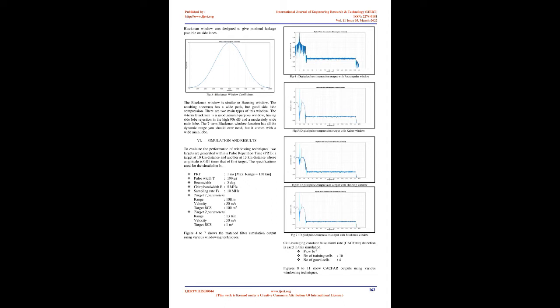The side lobe response of a strong sinusoidal signal can overpower the main lobe response of a nearby weak sinusoidal signal. Typically, lower side lobes reduce the leakage in the measured FFT, fast Fourier transform, output, but increase the bandwidth of the main lobe. The side lobe roll-off rate is the asymptotic decay rate of the side lobe peaks. By increasing the side lobe roll-off rate, spectral leakage can be reduced.